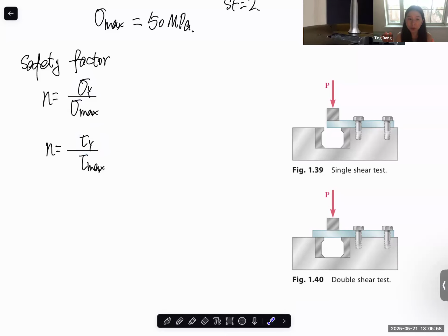Let's say you have an aircraft, you don't want during every flight some plastic deformation to accumulate, and your airplane fuselage getting bigger and bigger, because plastic deformation cannot go back to zero when the stress is released. After the yield point, the material is plastically deformed, so it can't go back to the way it was before.